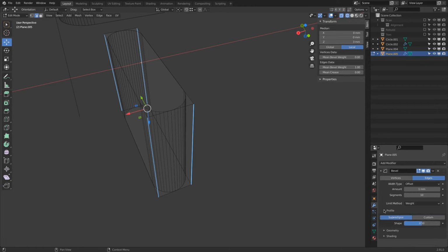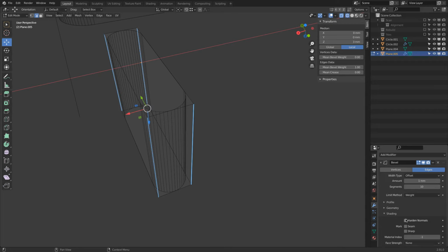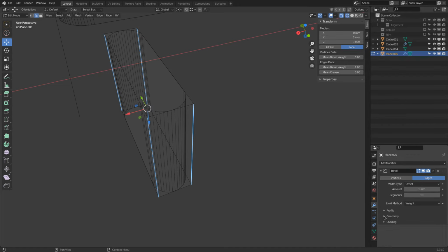Because we're going to use this for modeling, I was just looking, is there an edge merge possibility? I do not see one. So we have to trick a little bit. Because we have 2 edges here, this will give an issue with the Boolean modifier. So 0.9, 0.92, 0.93.